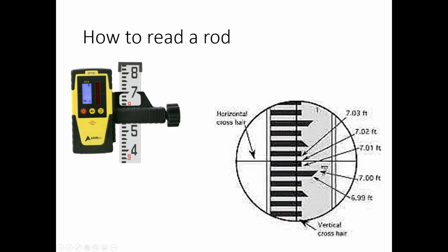I know this is a little grainy because I stole it from online and then blew it up, but basically if we look at the top of this bar, it's pointing in at 7 feet exactly. So if we traverse the distance in this white area to the bottom of this black bar, we're at 7.01 feet. So this bar is actually in hundredths. Sorry, I need to back up a little bit. Each of these gaps is a hundredth and not a tenth.